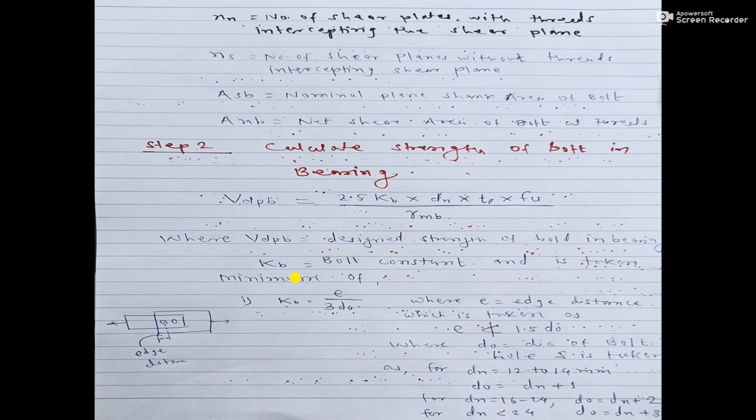These are different terms, we will see afterwards. Then step 2, calculate strength of bolt in bearing. First we have calculated the strength of bolt in shearing. Now we are going to calculate strength of bolt in bearing in step number 2.